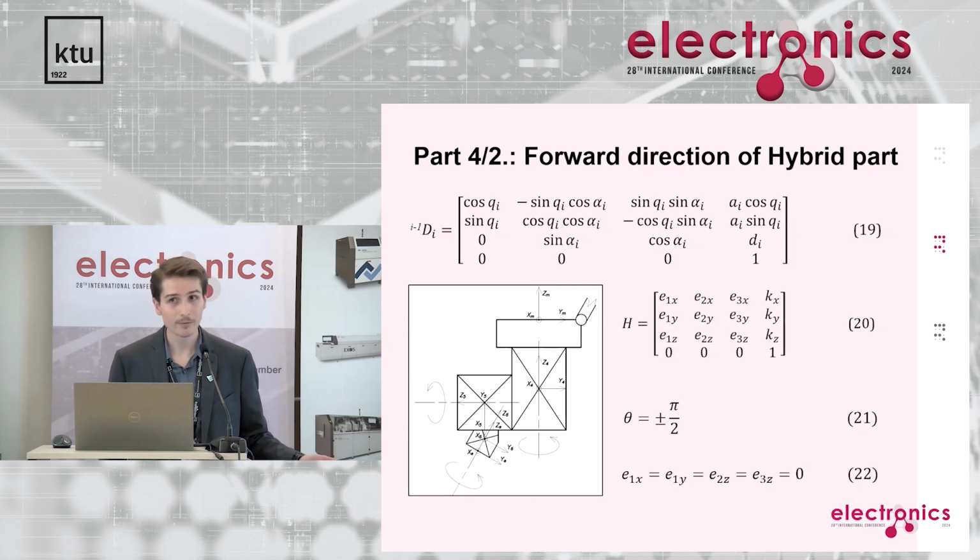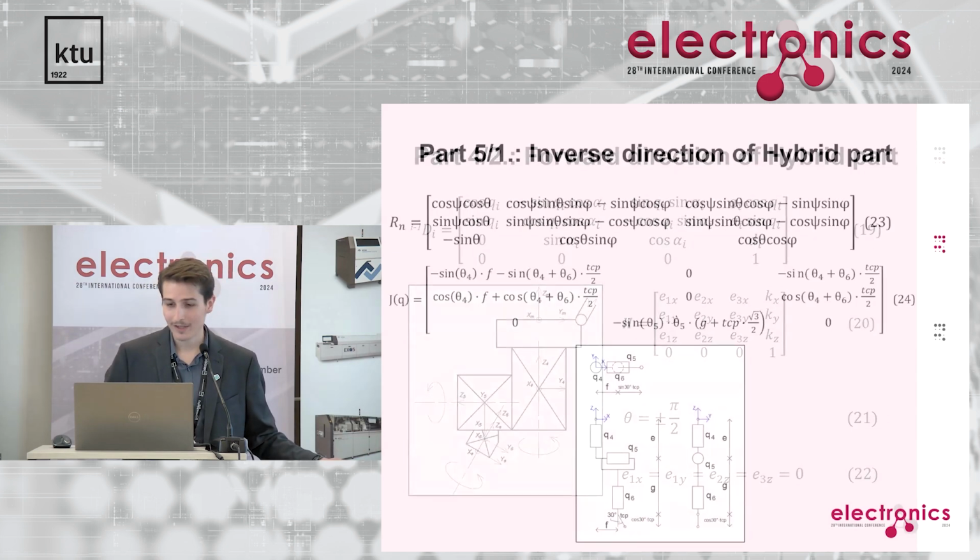However, we have another type of singularity, the second type, when one of the world coordinates, which is the rotation around the y axis, is π/2 or minus π/2, so 90 degrees. This is a singularity. This is the only type of singularity which is handled by the manufacturer officially. I will show how.